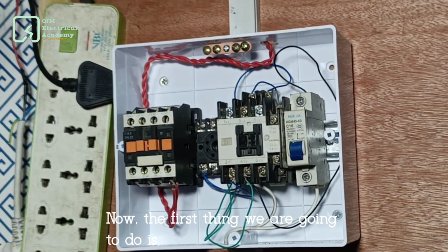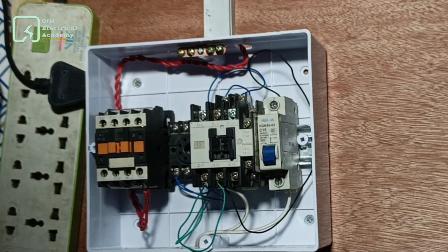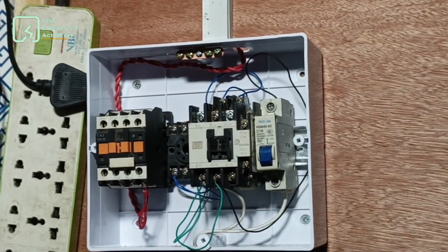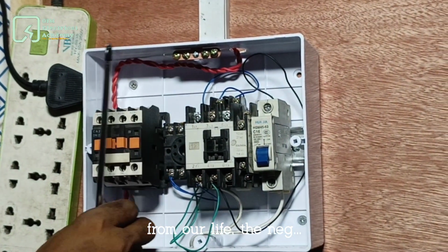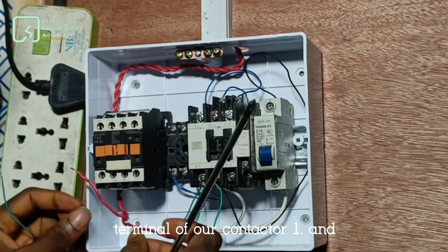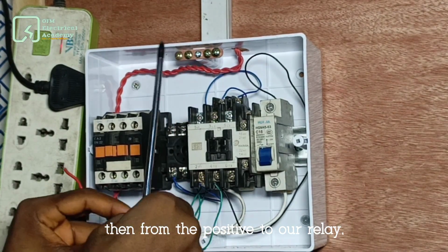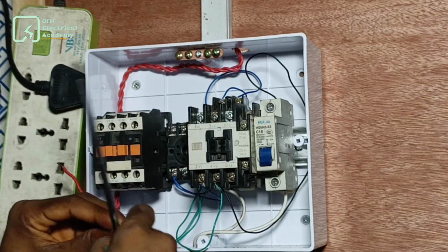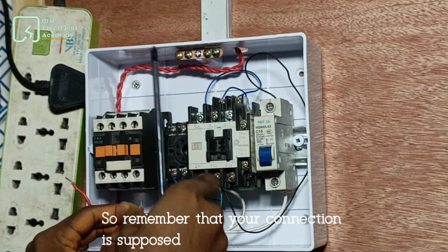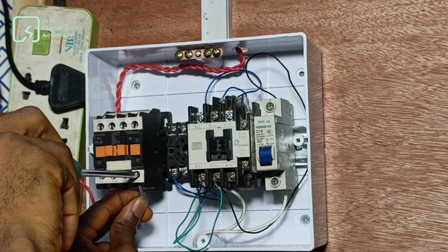Now the first thing we are going to do is these are generator cables. So we are going to connect it. When we connect it, we will send one wire from our live, the positive, from the negative to the coil terminal of our contactor 1, and then from the positive to our relay. So remember that your connection is supposed to be at the normally open side of your contactor 2. So find out the number and connect.